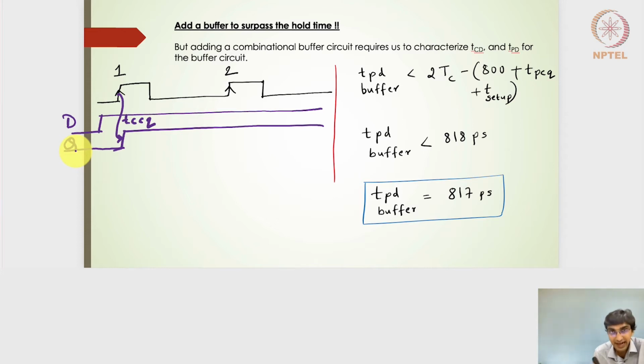And then this will be the output of the flop. After that, there will be an adder block. There will be 3 muxes block. So I'm going to say that all of them is a contaminated output. So I'm going to consider this as the contamination TCD, which is nothing but a contaminated delay of all the 4 combinatorial blocks, right? So if I consider this TCCQ plus TCD.